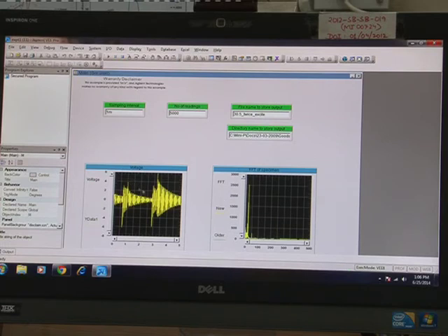So, you can see the impact of the hammer is producing a voltage response in the piezoelectric patch. Now, the reason we are getting two different responses here is that in the 5000 readings, during this 5 seconds, the hammer has hit the cantilever beam twice. That is why we are getting two impact responses, and this plot gives the FFT response of this voltage.